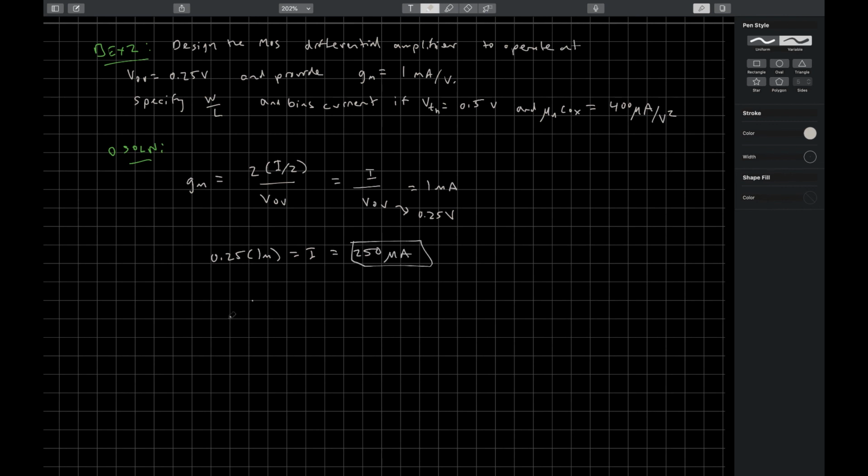If I assume that the transistors are set so that the differential input voltage is 0, then I know that ID for either transistor is just I over 2, which is equal to 1/2 mu n Cox, oxide capacitance, aspect ratio, V overdrive squared. And I know all of the information about this except for the width to length ratio, the aspect ratio.